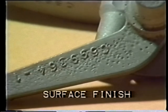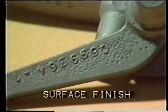Inclusions in castings are pieces of foreign material which are trapped within the casting during solidification. The foreign material is generally non-metallic in nature and is less dense than the metal being cast. Common sources of inclusions are pieces of mold material, such as sand, crucible material, and metal oxides, or slags. Unacceptable surface finishes can be caused by poor mold building practice and excessive process temperatures.